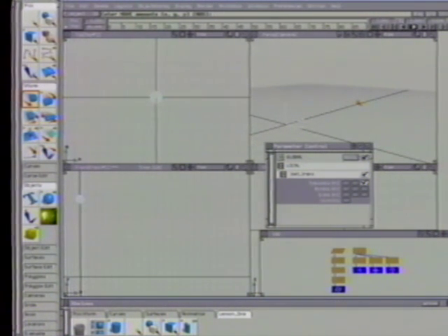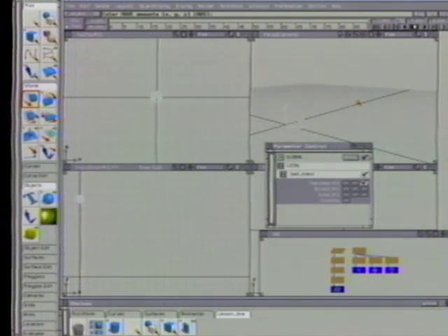Click on the Stop button to stop the playback, then click on the Go to First button to return to frame 0. You will now give the ball some lateral movement by animating it in the X direction. This action requires that you change your parameter settings for the selected node from Z translation to X translation. This process of choosing a parameter, animating it, then moving to another parameter is a good way of slowly building up an animation while maintaining control over the parts.